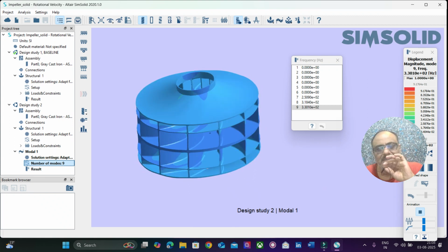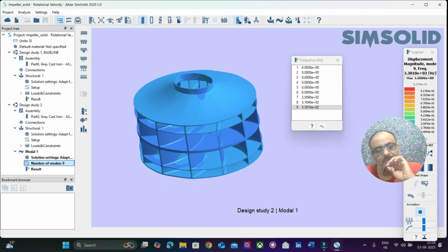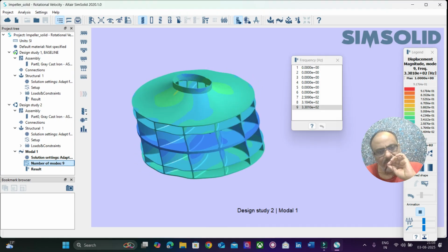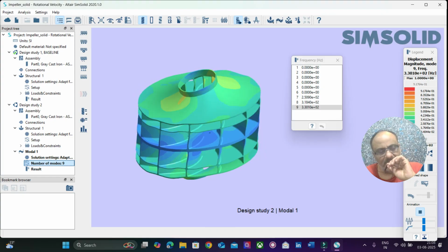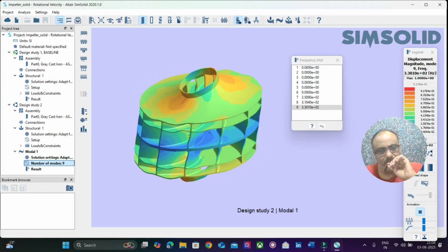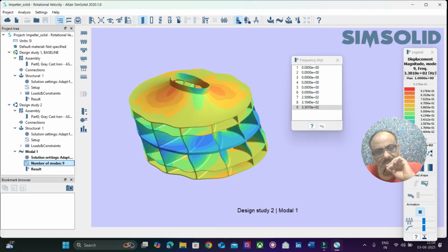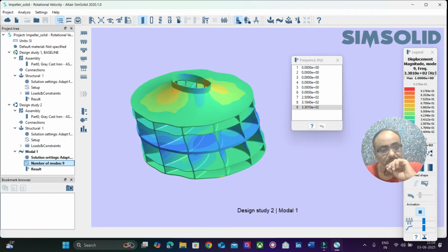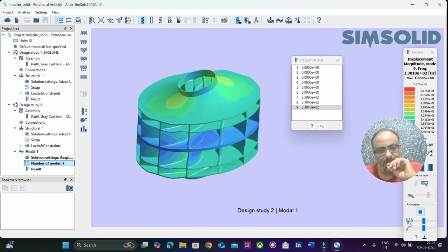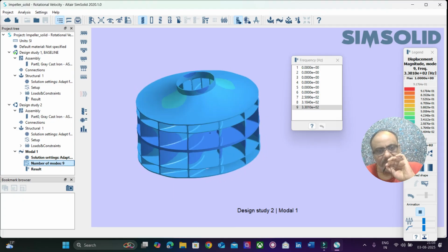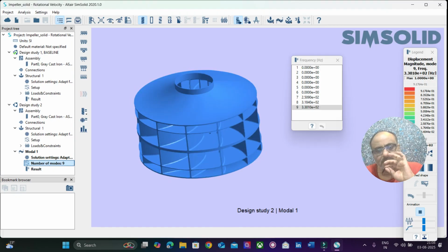The noise or vibration induced from that is called structure-borne noise. Now, these structure-borne frequencies are more than sufficient to fail this particular system. That is why, in the next consecutive steps, we perform a random vibration analysis. Before that, a forced frequency analysis is done. In the forced frequency analysis, we apply the same boundary conditions and find out what the frequencies are. If those frequencies match the normal modes, the natural or fundamental frequency you see here, then the structure is sure to collapse. But if the frequencies are not matching, then the structure is safe.